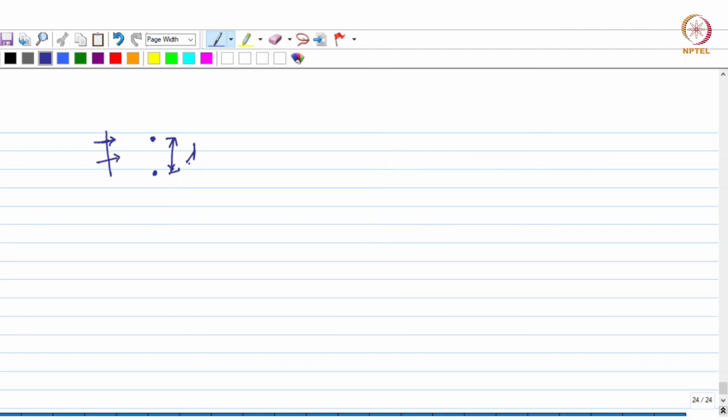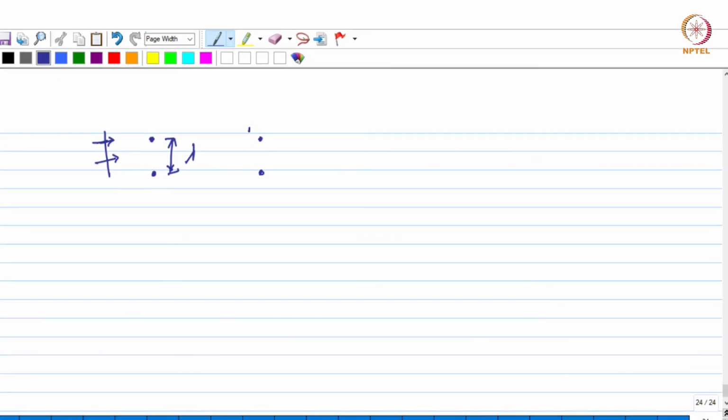With a mechanism like that, the dislocations will bend and bypass the particles by bending in between them. Okay, so in order for that to happen, the dislocation line has to bend, as I said. So as it encounters the particles, the dislocation will try and bend around these precipitates. Something like this.